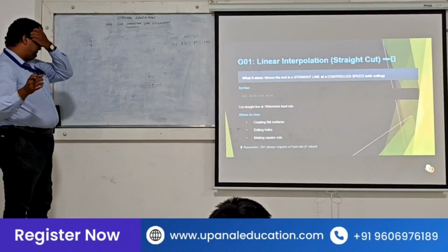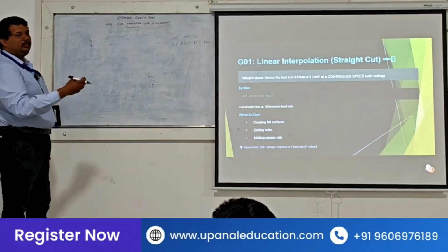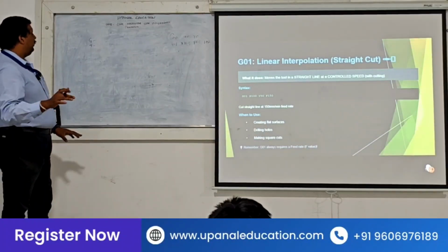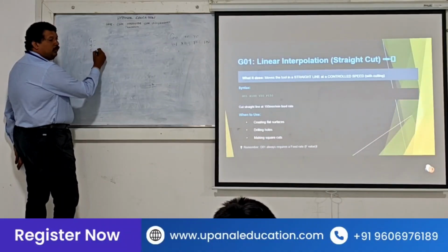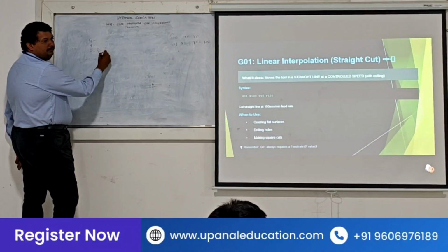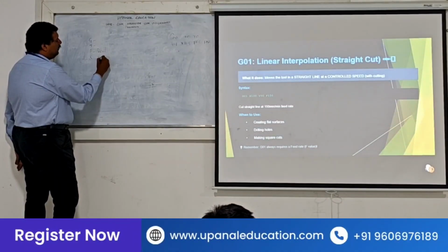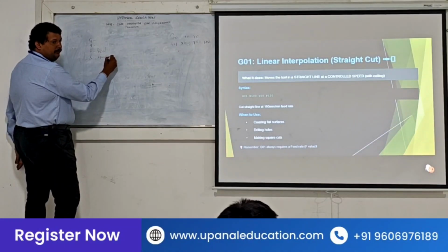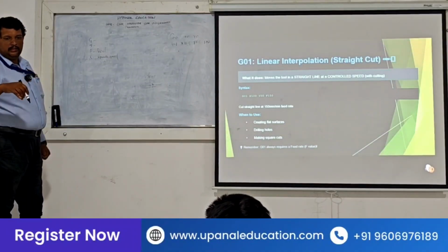I told you, like in a vehicle it will be headlight on, wiper on, all those. So here it will be coolant on, all those. We'll explain. Then F is for feed, F-E-E-D, feed. S will be for spindle speed, at what speed the spindle should turn.